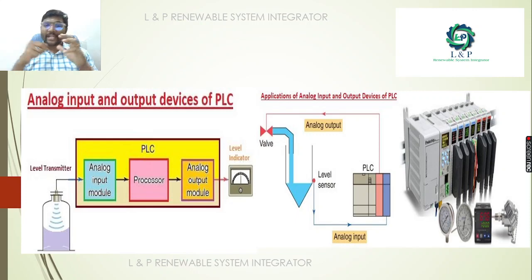The modulating valve, because in the modulating valve we go through two things: we have an analog output signal, and also an analog input. Say, for example, if you are controlling a valve, you will provide some analog output. It can be 4 to 20 milliamps or 0 to 10 volt. At the same time, if you want confirmation that it operated as per your command, as per your control, in order to monitor it you will take the feedback. That feedback you can consider as an analog input.